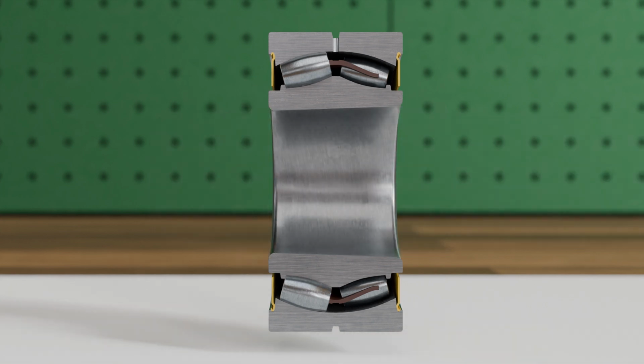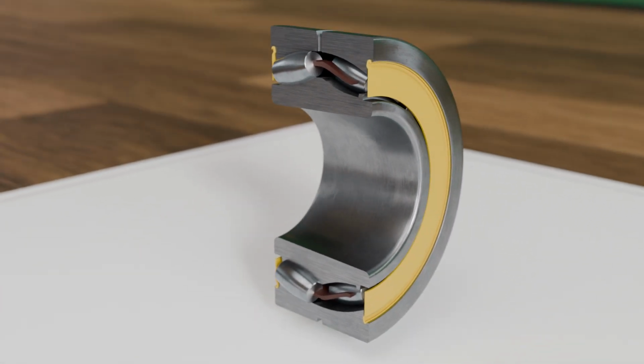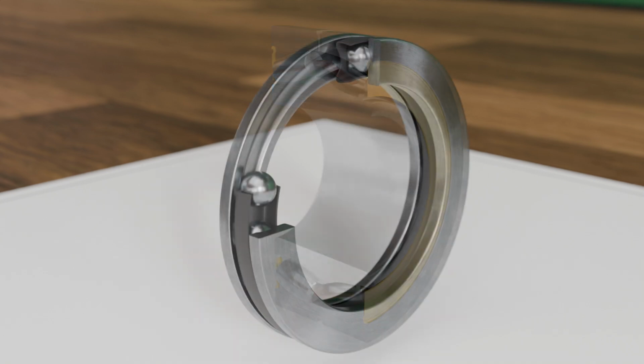The bearings considered so far are mainly designed to support forces in the radial direction and are therefore called radial bearings. In addition, there are also bearings specifically designed to accommodate axial forces. These are generally referred to as thrust bearings. Depending on the rolling element used, different types are distinguished, each with its own specific designation.